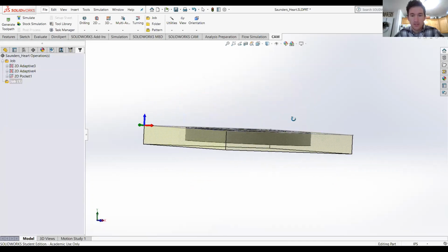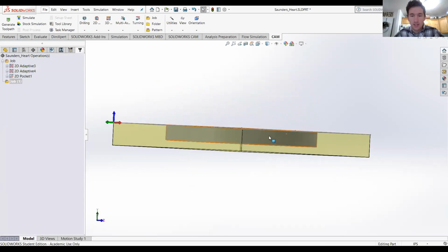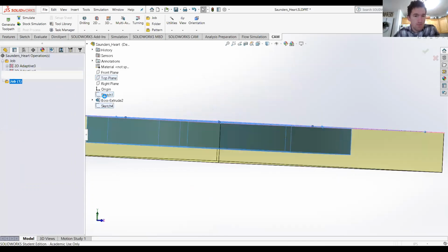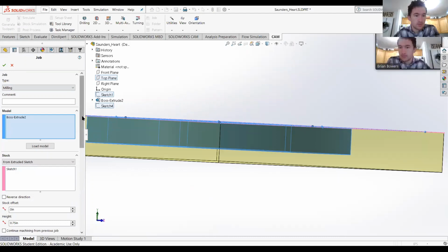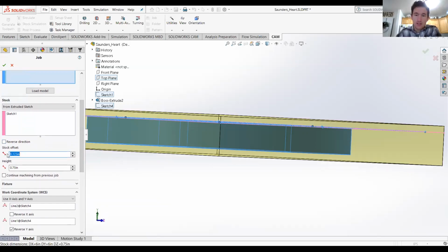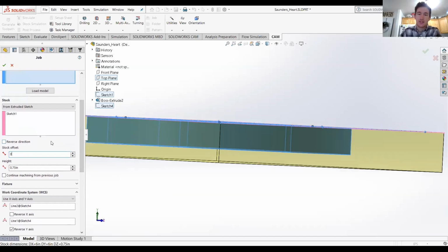Another thing I want to mention is you can see that I defined 3/4 of an inch deep or thick material, and that part of that design is only a 1/2 inch. If you want to edit the way this sits, back in here you have this stock offset option, and that'll just take it up from your piece. We're going to leave that at 0.